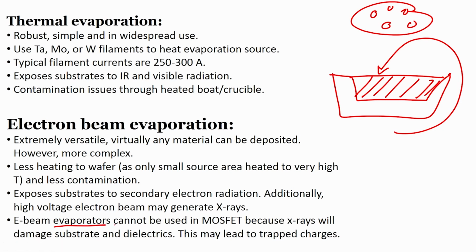E-beam evaporators cannot be used for MOSFETs, because X-rays will damage the substrate and dielectric, and this may cause trapped charges in MOSFETs. So, unfortunately, we cannot use e-beam evaporators for MOSFETs, because these X-rays will damage your dielectrics and substrate, and this may lead to trapped charges.